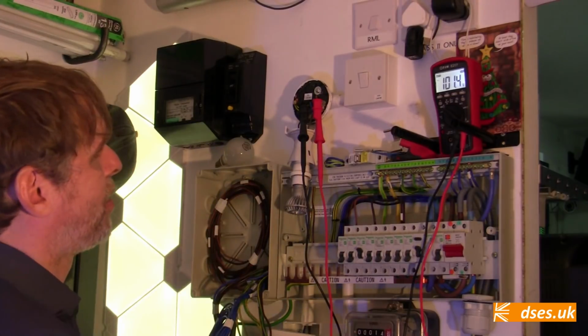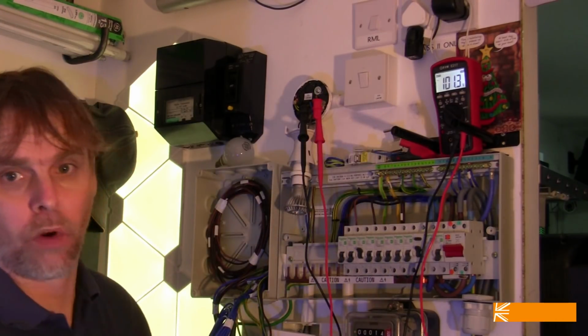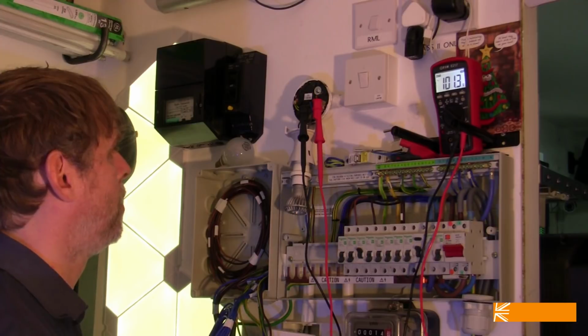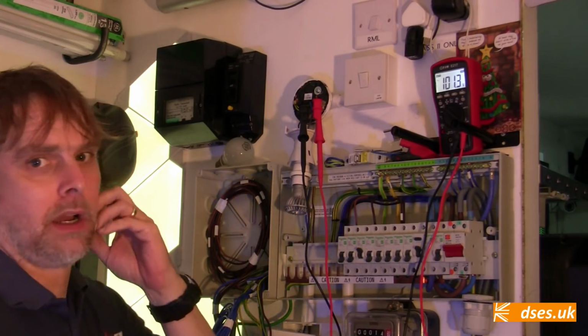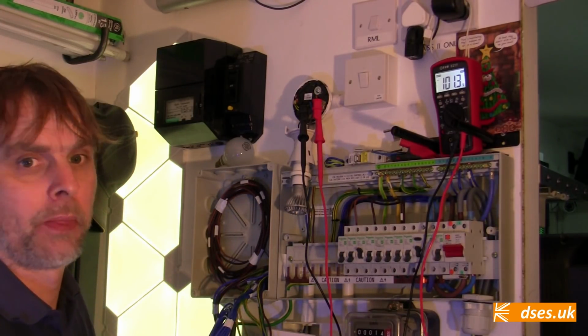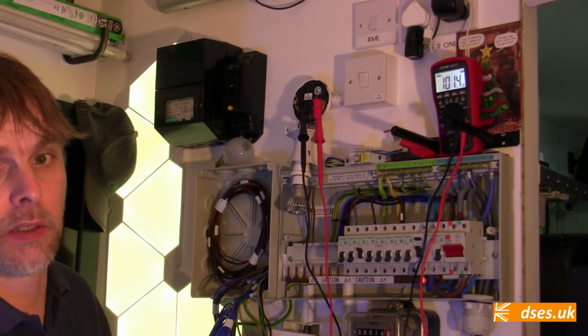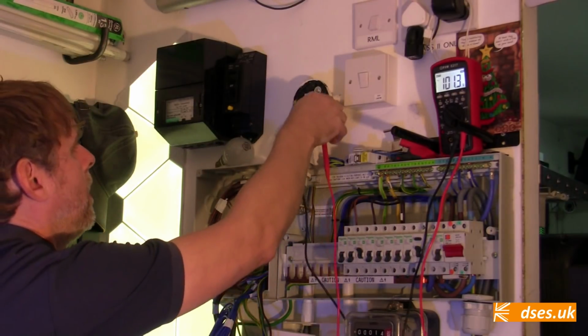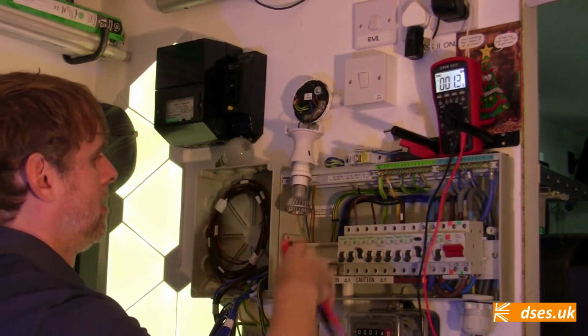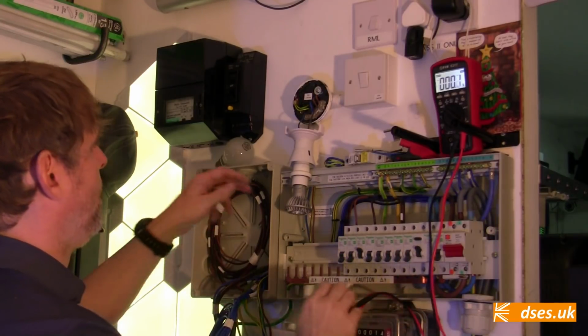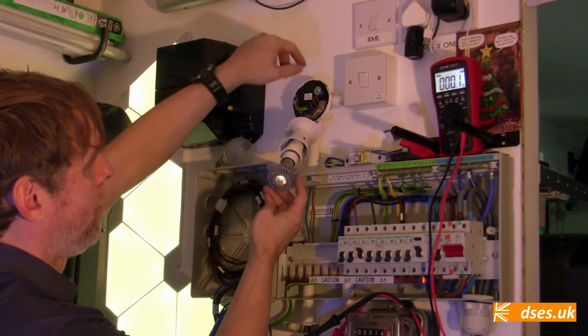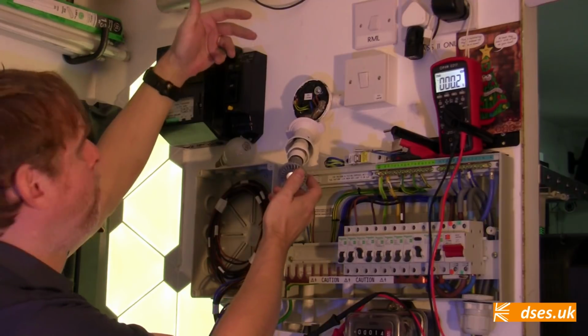So even if the voltage across here is as high as 101 volts as it's showing there, I've already shown that the current is tiny, and that even the connection of a voltmeter seems to squash it. Therefore, if I disconnect that, I should be able to touch between the 2 points here quite safely with no ill effects.